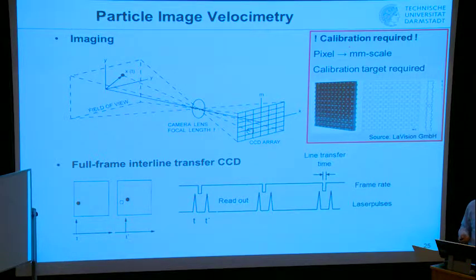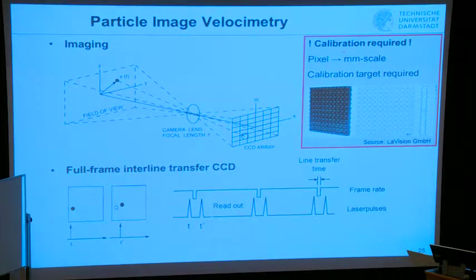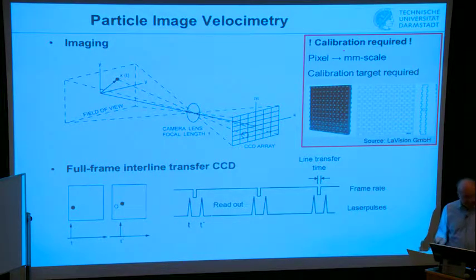And so another piece of advice is that in PIV, within one interrogation volume, the displacement should be on the order of 25% of the length of this interrogation volume. And that brings you already to the point when you have different velocities in your field of view. Maybe you have a backward-facing step, high velocities in some locations, recirculation, and negative velocities as well, including maybe regions where you have more or less stagnant flows. There, PIV suffers from the dynamic range. So this is a critical issue.